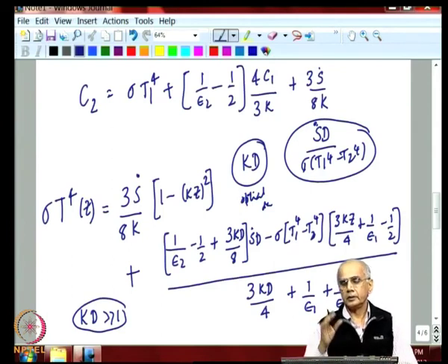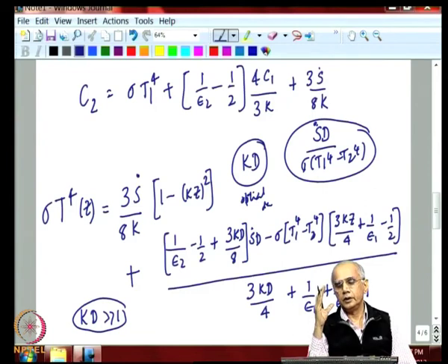But the other parameter, the relative importance of the internal heat generation to the wall heat transfer, is driven by the second parameter, and so if that parameter is important, then the linear term will play a role, while if this term is small, then our quadratic term created by volumetric heat generation will play a role.